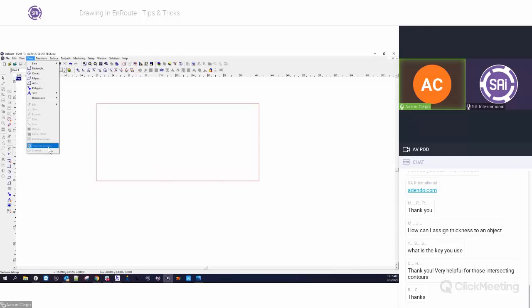So typically we say if it's something that has grayscale, just take it into any program. You can probably use Paint 3D that's built into Windows, and you can probably flip it to black and white, and that'll probably help. But yeah, you can use Vectorize Bitmap, and it does a really good job of vectorizing all your lines. And then once you vectorize it, if you need to make any changes, you can use your point editing tools to change anything in your drawings and stuff like that.